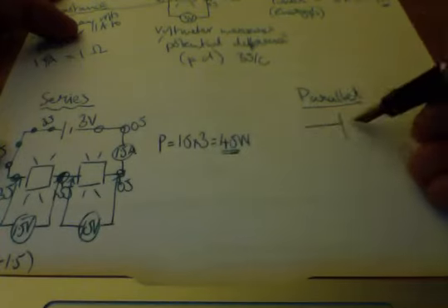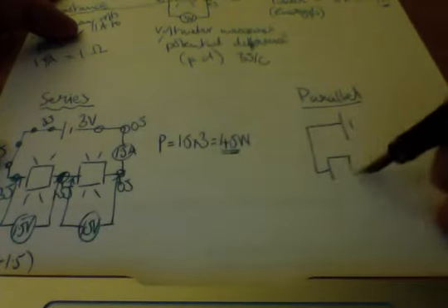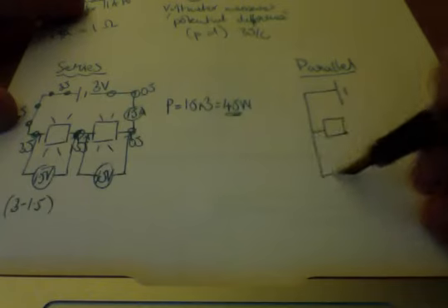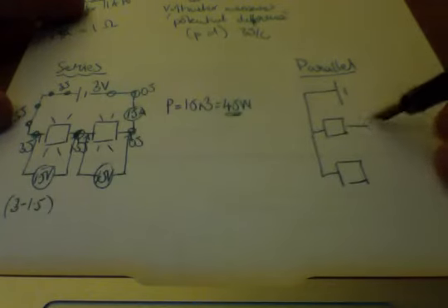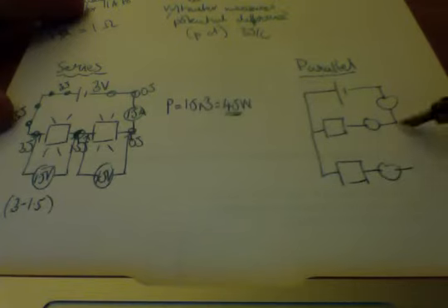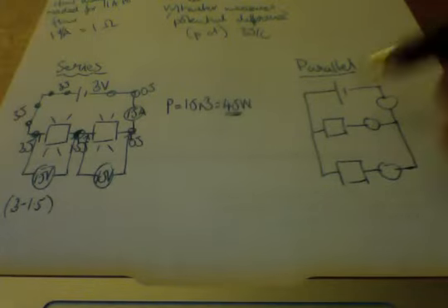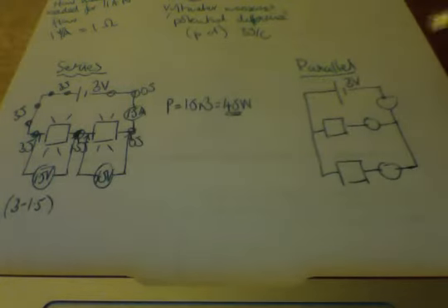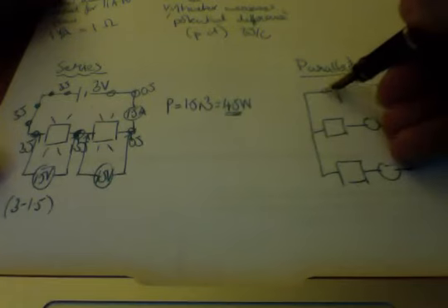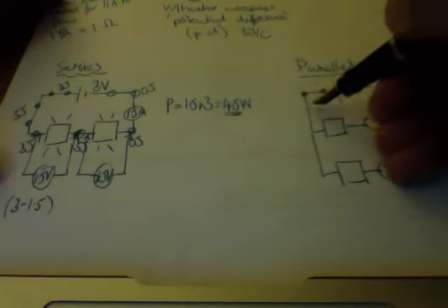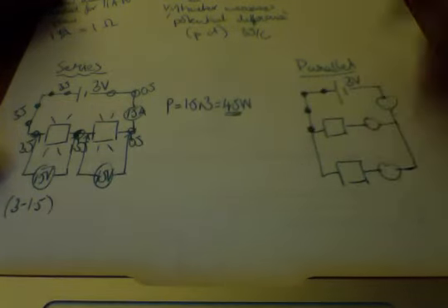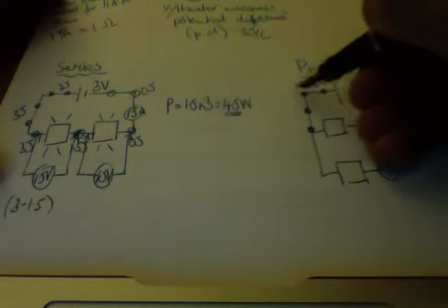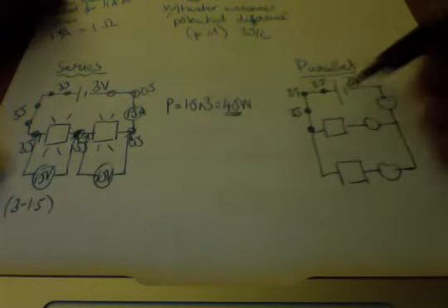And once again, I'm going to use exactly the same components, but place them in a parallel combination. I'm going to place ammeters on each branch so we can see what's taking place. The resistors are identical, the same cell is placed in, so now what happens? Okay, the Coulomb comes out of the battery. It comes around and then it hits a junction. It has 3 joules, of course, it has 3 joules all around because we've got a 3-volt supply.